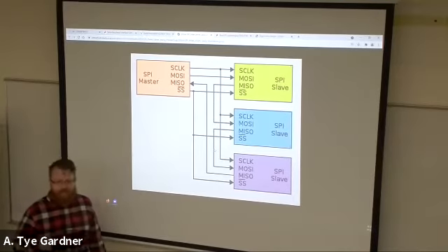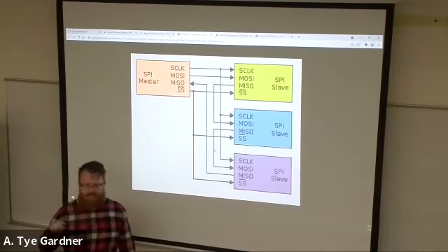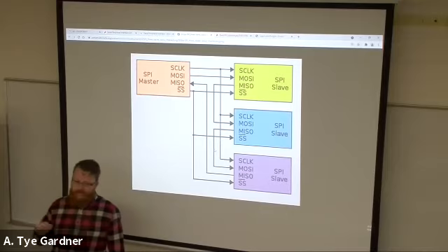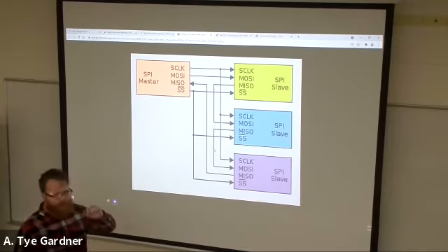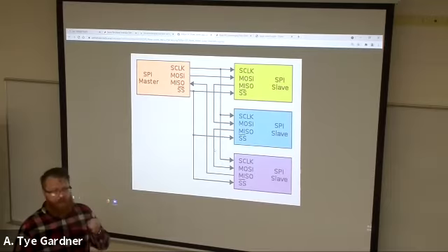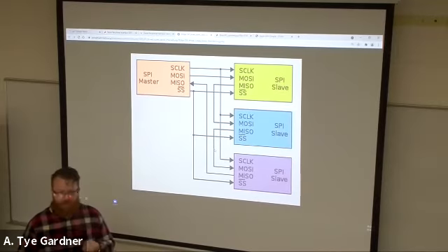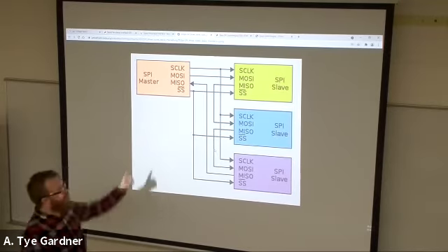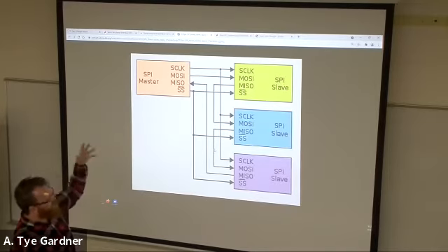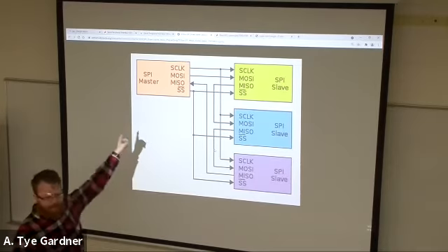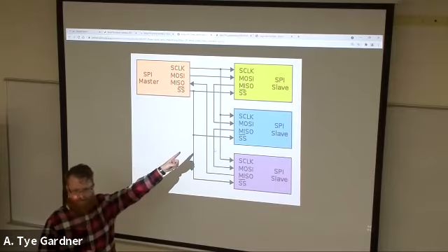The other one that you will see is SDO/SDI, serial data out, serial data in. The reason that this one exists is for the same kind of reason, but it lacks the clarity of which perspective you are coming from, right? Because MISO and MOSI or COPI communicate the perspective. It is the master out, slave in, okay?